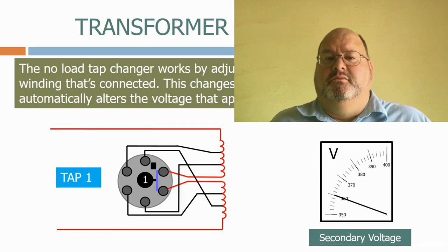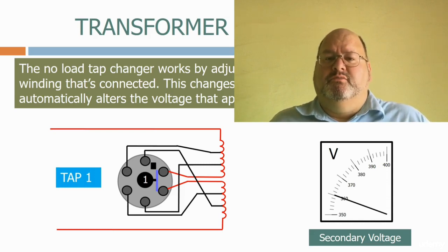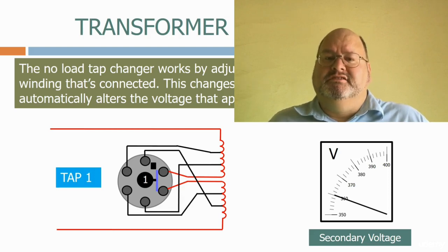The majority of transformers provided on the distribution network are off-load tap changers, which tend to be set at a fixed tap for most of their working lives. Over time, if a section of the distribution network is becoming overloaded due to the types of load changing, or more customers being added, it may be required to increase the system voltage slightly to compensate for the strains on the network. All of the transformers feeding that part of the network will then be taken offline, one by one, and have their tap changers moved up a tap before being reconnected to the network.